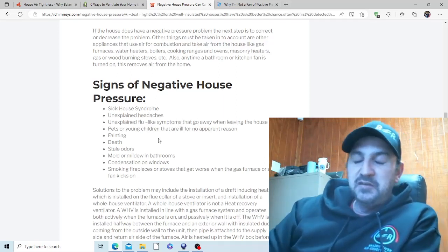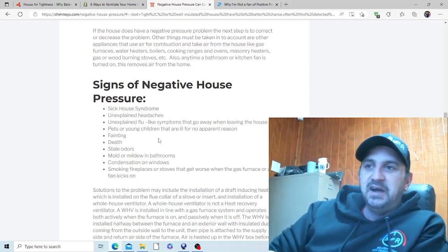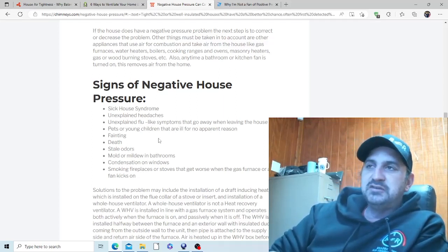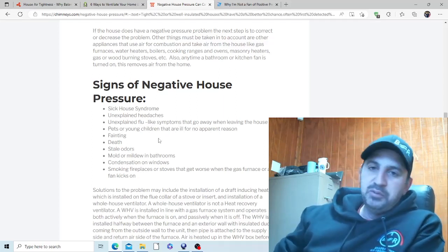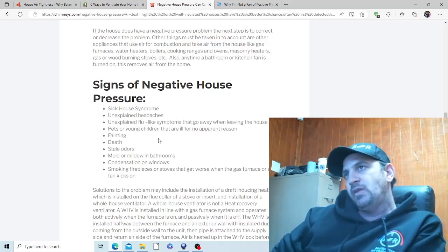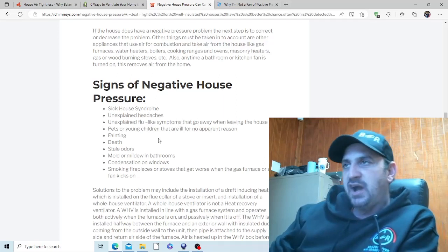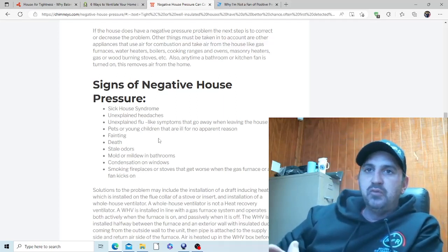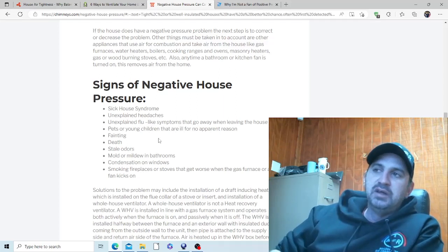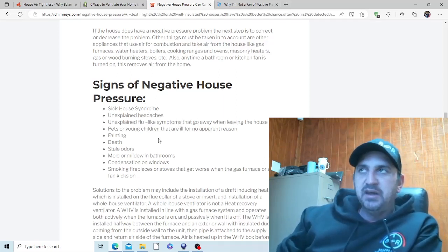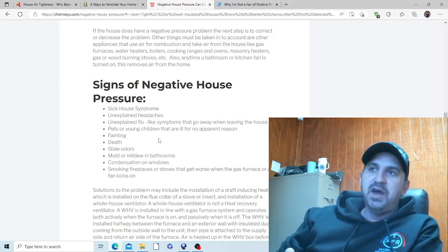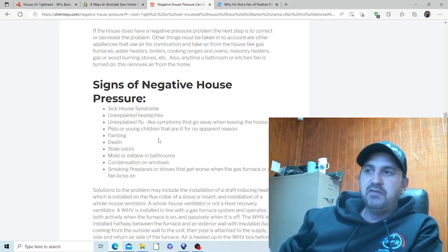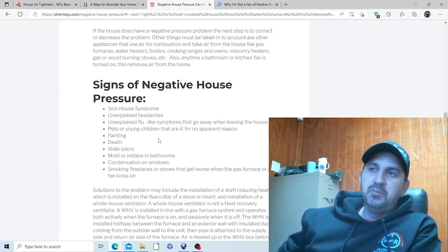All of that insulation on a 50-year-old house that's been sitting there in the walls untouched because you haven't redone your sheetrock, that have mold or mildew or whatever in there. That stuff is all polluting your air as it comes into your home. So a negative pressure house is not something that you really want, but I would say it's probably as common or more common than any other type of system, just because anytime you turn a bathroom fan on or a kitchen fan on or whatever, you're essentially making your indoors a little lower pressure while making the outdoors a little higher pressure.